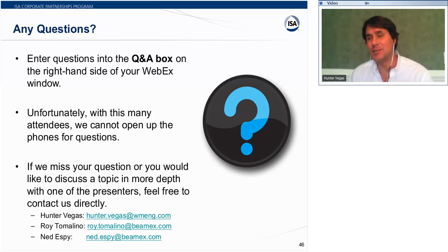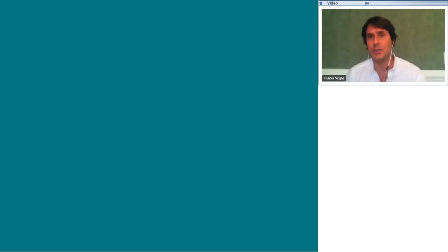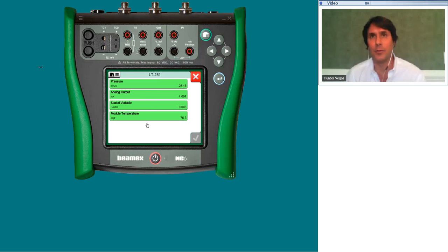What we didn't really get into, and Roy is going to show you here in a second, is my personal experience. You can calculate what the span is going to be. You know the liquid level, you know the gravity. In this case, we said it's going to be 25 inches. We're going to say 0 to 25 is what you're reading. Now you're just trying to adjust the 0. What I typically do in an application is get the seals installed where they need to be. You vent both the seals, and at that point you read what the transmitter is reading, because you're going to have the liquid pushing on both sides. The height of the seals matters. The fill fluid matters. And while you can try to calculate all that, it's way easier to just get a reading on it and say, okay, I'm reading minus 28.46 with both of them vented, so my calibration is going to be minus 28.46 plus 25 inches, which is minus 3.46. And that's how Roy did this.